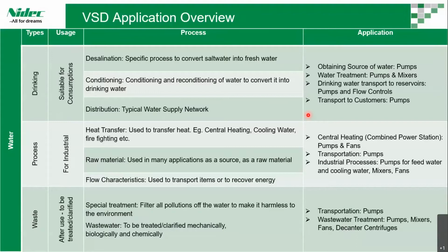When we come to the VSD, why do we need a VSD? Basically, this is one of the points we are going to discuss in detail. It is about the energy conservation opportunities available in water and wastewater. In any budget, whether municipal or government, energy is a single line item that plays a major role, especially in water and wastewater. So we can save nearly about 10%, just as an approximation for the complete water and wastewater system.